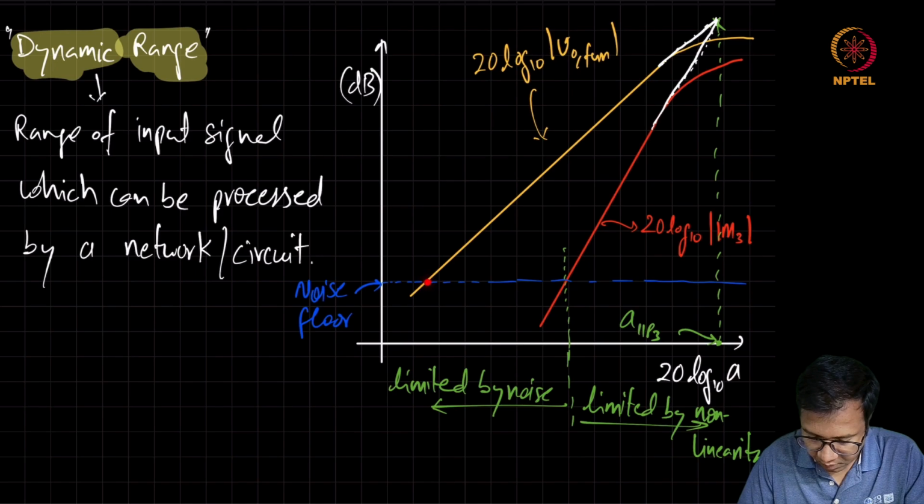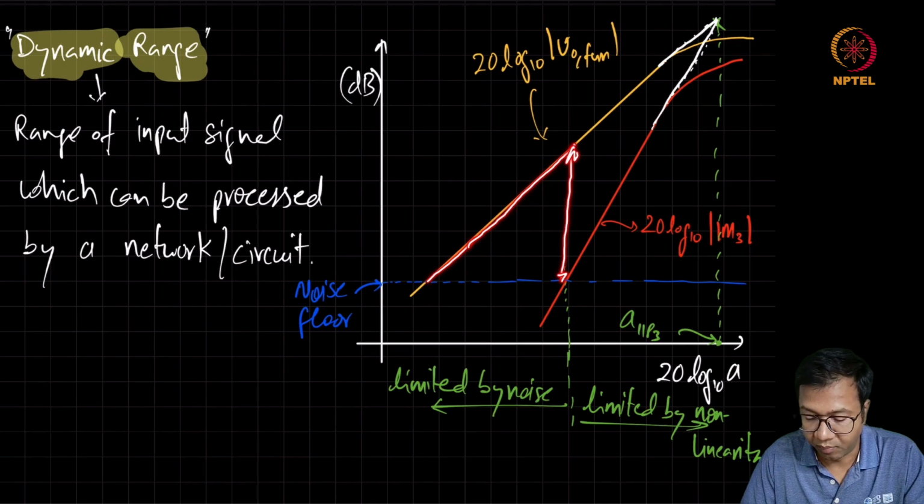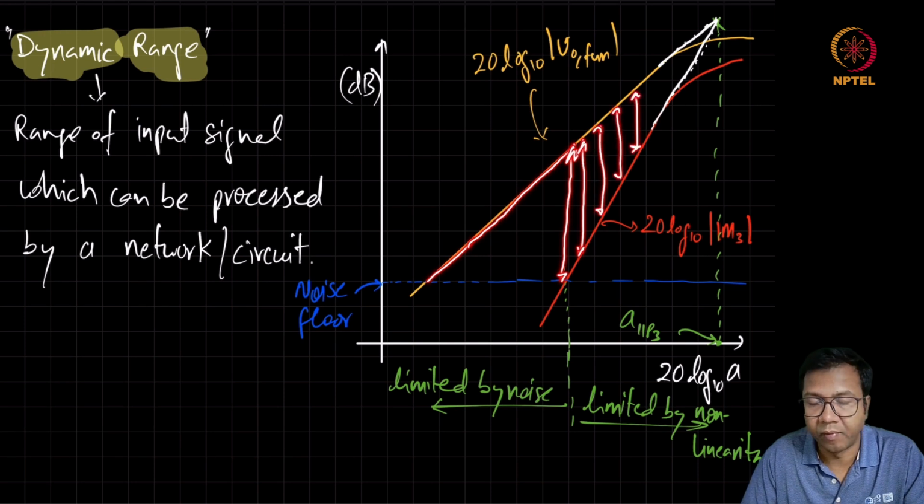So it helps when we increase the input signals because our output is also increasing. But beyond a value of input signal, it doesn't help us, as we can see that these undesired intermod components are going to come into picture, and effective signal with respect to the undesired components, that ratio is going to only reduce.